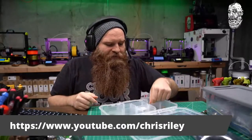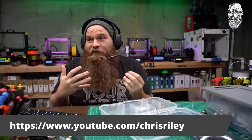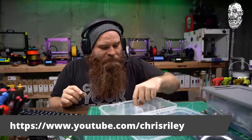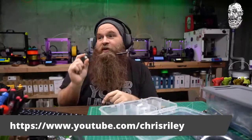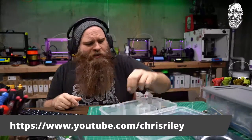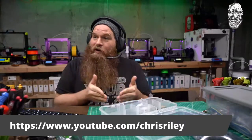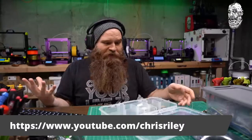If you're using one of these older chips on your motherboard, you're never going to get things like sensorless homing. These are features that won't matter to you because this chip can't do it. Now, if you have a 2209 or a 5160 or whatever, you can run sensorless homing, because those chips, like a 2130 or a 5161, all have sensorless homing built in. So these are features you can't use if you don't have the right chip. You might have sensorless homing on your chip, but you may not want to use it. So again, first your board, then your stepper, and then we can talk about features.